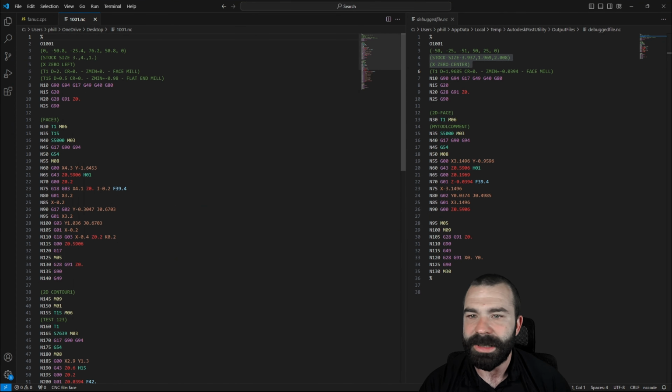So as I post out, you guys are going to see this G code is populated. Our x0 is on the left side of our part. Again, that's X0 on the stock is the left side of our part. So as we're using the stock edge, right, we can define whether we're using stock or whether we're actually using the model now as well. There will be limits on what you can do with this, as you guys are going to find out. The limit is if you put your origin in a weird location, you're just not going to know where that is.